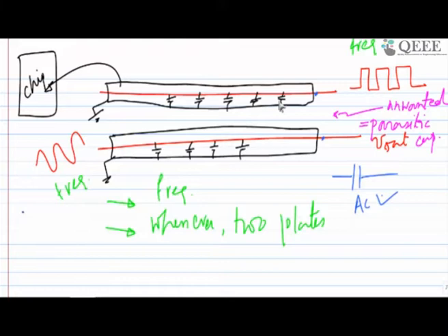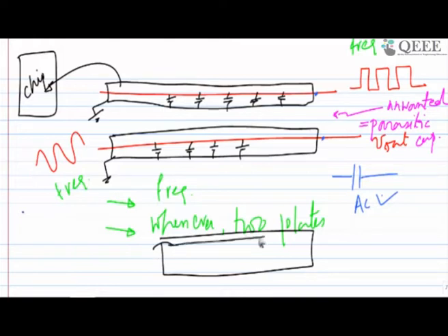Let's say we don't have coaxial cables available, or you are only talking about something which you are making on a breadboard, and on the breadboard there is one line which is, let's say, horizontal, and these are the verticals. This vertical has the clock and this has your sine wave. So definitely they will talk to each other if you are keeping them near and near, or you are not making a clean circuit. So this is the thing you have to make sure. And the solution which I was showing, maybe you have seen the same thing in BNC cables.